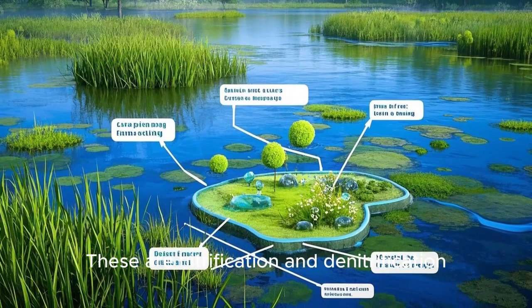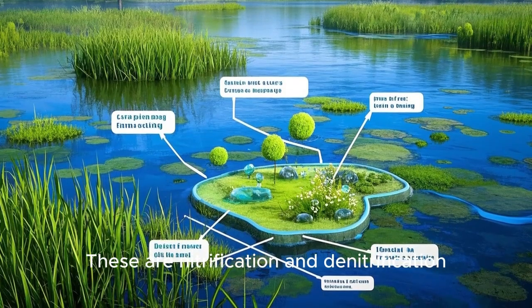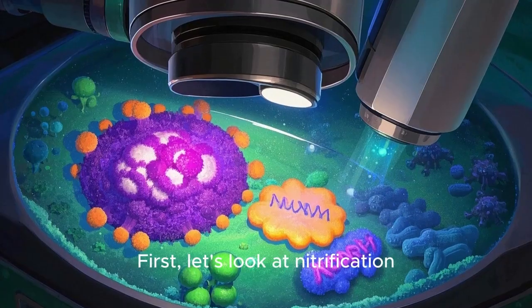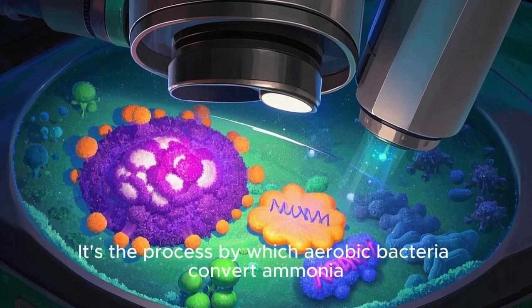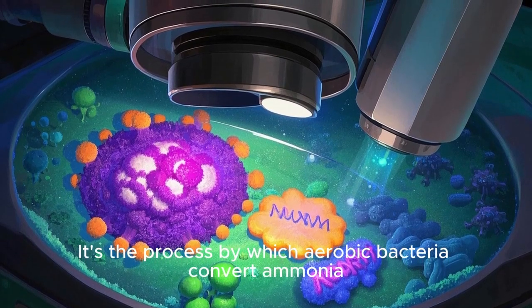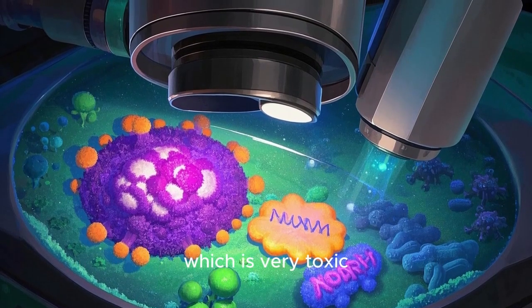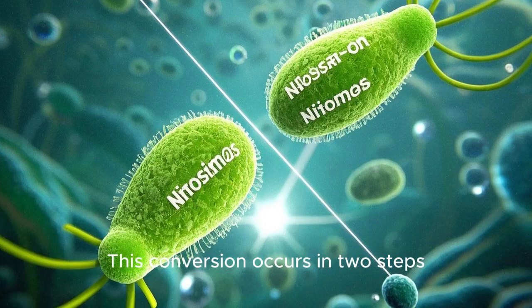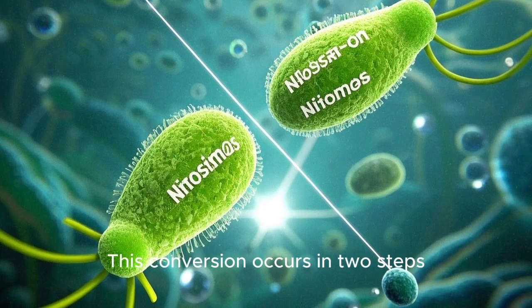Besides this, there are two other crucial processes that occur in the wetland's aerobic and anaerobic zones. These are nitrification and denitrification, which help remove nitrogen from the wastewater. First, let's look at nitrification. It's the process by which aerobic bacteria convert ammonia, which is very toxic, into nitrite and then into nitrate. This conversion occurs in two steps.